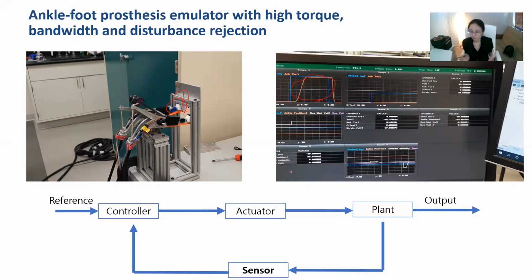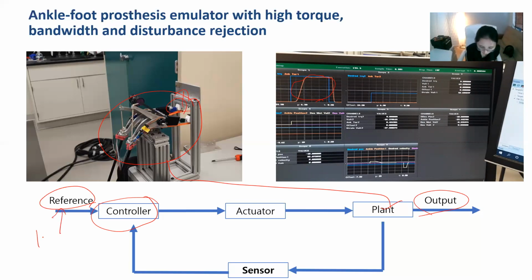And the actual torque tries to reach the desired torque. And how can you do this? So this entire thing is a plant. And then there's an actuator, which you saw before, and the controller commands the control input to the actuator by comparing the reference and the output. So in this case, the reference is blue and the output is orange torque, in the previous slide.